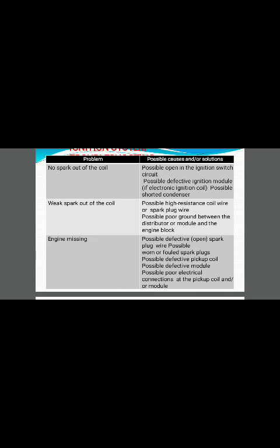The next problem may be engine missing. Possible causes are a defective spark plug wire, a burned or faulty spark plug, or a defective pickup coil. You have to also check for a defective module. You should also check for poor electrical connections at the pickup coil.